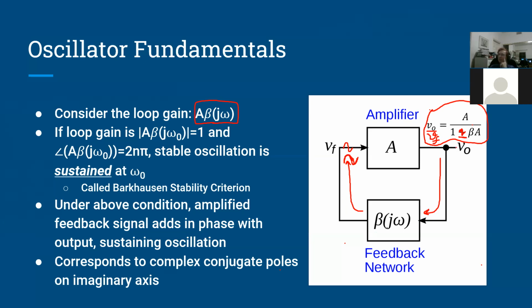It's an unstable circuit. So what if we made the loop gain, beta times A, be 1? Such that when we go around in a loop, you're not increasing the input, you're just keeping it as is, so that the input remains a fixed amplitude. The output will remain a fixed amplitude because the output is just A times whatever is at the input to the amplifier.